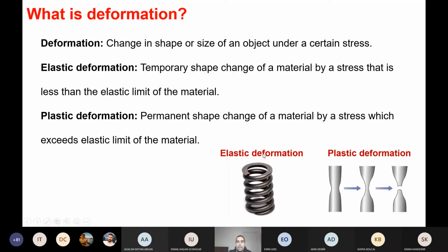That is why I added a spring here. So the material works basically like an ideal spring, that it retains its shape. Plastic deformation, on the other hand, is completely opposite. Here we get a permanent shape change under a certain stress or loading. When we have plastic deformation, the shape change can be named irreversible. Of course, there's a little bit of spring back, which reverses the deformation, but it's a marginal amount. If you look at the main result, it's a kind of one-way ticket.